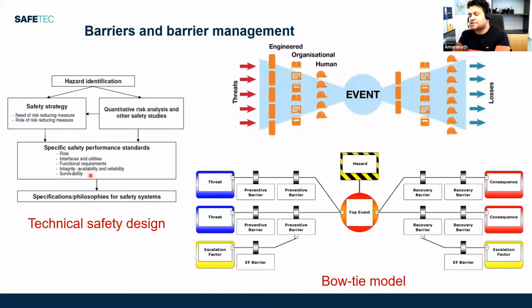The safety critical system should be reliable, and for example, isolation valves should have a very high criticality level to ensure that they will function in case of accidents. There are different types of safety integrity levels, what we call SIL levels, for safety components that we use in the offshore oil and gas industry.